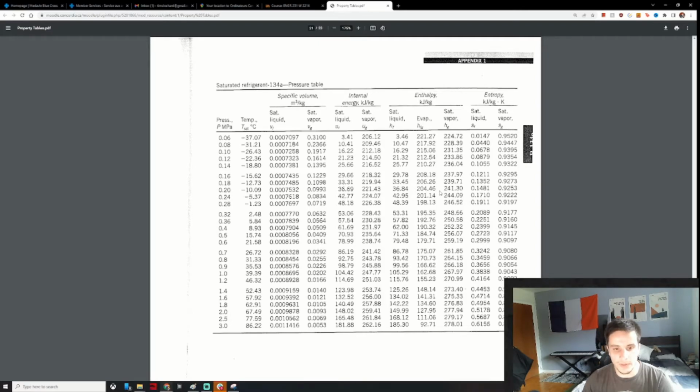Actually, since we're looking for the temperature in the second state, we wouldn't have had to do all of this exercise using the first law equation. They immediately told us that it was 700 kilopascal, and if we assume that it was saturated vapor, so 0.7 megapascal, we could just plug that in as your saturated temperature, since we know that it's in the mixture phase. But in this case, it's not. We can't make that assumption. I mean, that's the whole point of the exercise.